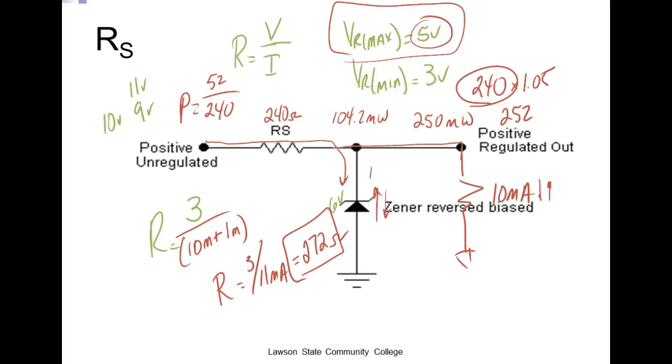Well, what was the problem? They were using quarter watt resistors. 30 volts, quarter watts. I forgot what the value was, I think it was 100 ohms. So 30 squared over 100 ohms greatly exceeds quarter watts. And it was burning them up. So they were looking at the value of the resistor, and they weren't concerned with the watt rating. So you have to make sure you understand these wattage ratings on resistors, or you're going to burn a bunch of them up. Or else you're going to choose one that's too big and pay more money.